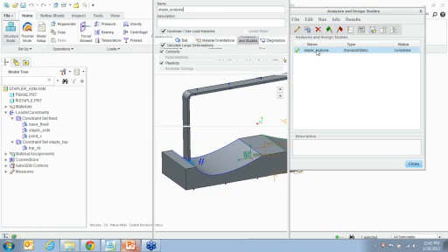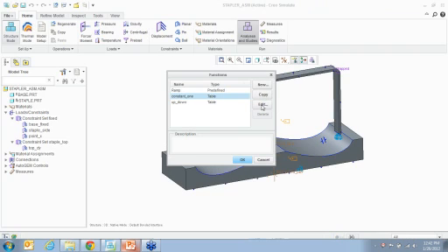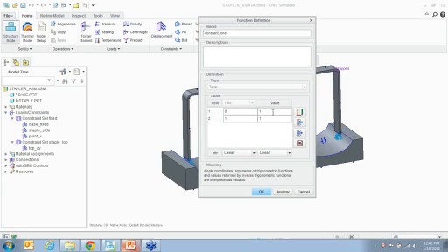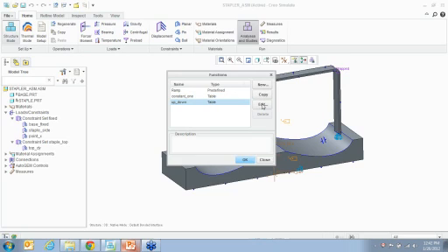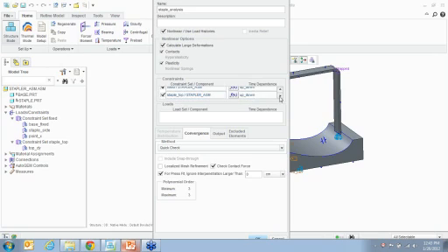In our analysis, I want you to see I have two constraint sets right here. You have constraint 1, which is for the fixed, where everything's fixed. You notice that it starts at 0 and it ends at 1, and the value, it's constant, it's always applied regardless. Now let's look at up down, and I want you to see here that I have 0, 0.5 and 1 as the intervals. At 0 the value is 0, at 0.5 the value is 5.8, and at 1 second the value is 0 again. So what happens here is that this up down is actually applied to the tabletop constraint.